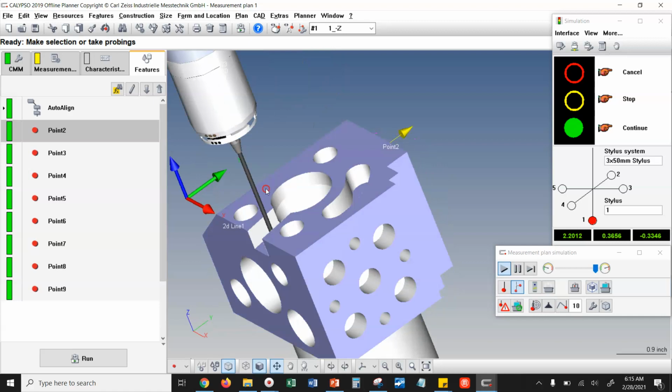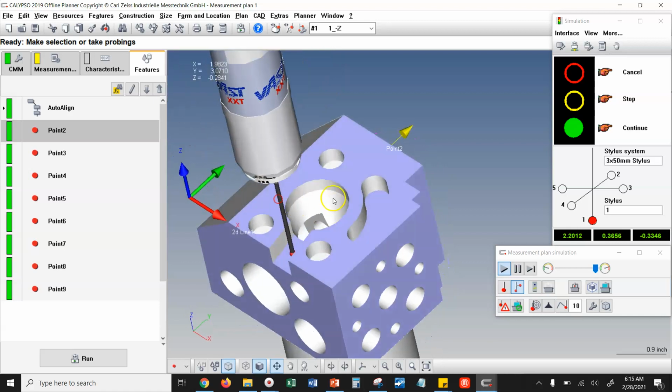So next, measuring point 2. Well, that's at the back of the part. Well, I just measured the top plane, the front, and then the left side. So if we're just moving clockwise, yeah, that's relatively path efficient. And we measure point 3 on that edge, then point 4 on that edge, 5, 6, 7. All right, so it looks like we already have a path efficient program. If we didn't, we could just grab any of these points and just pull them around to wherever we want. Right?